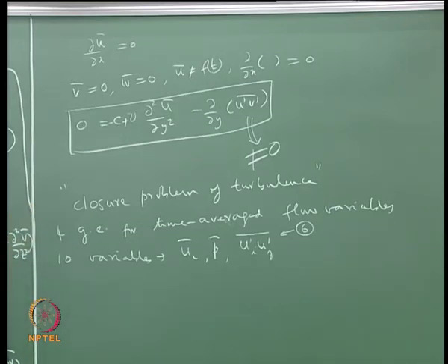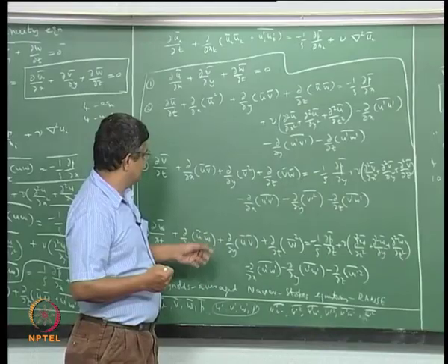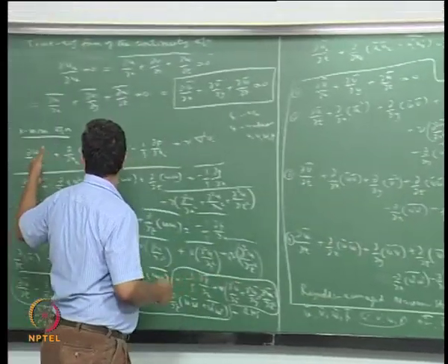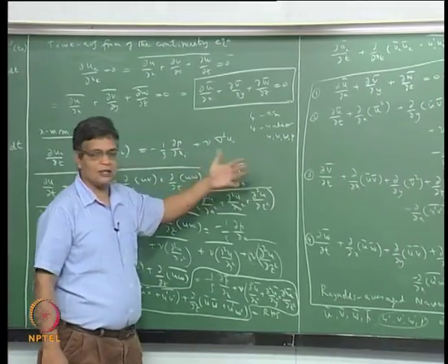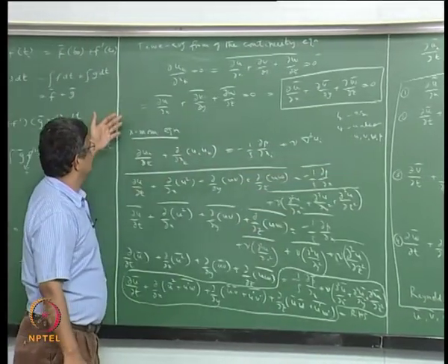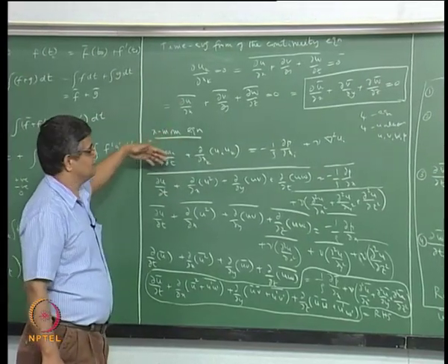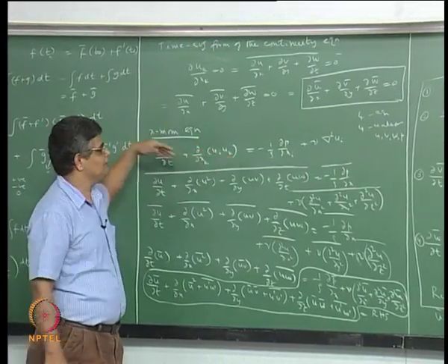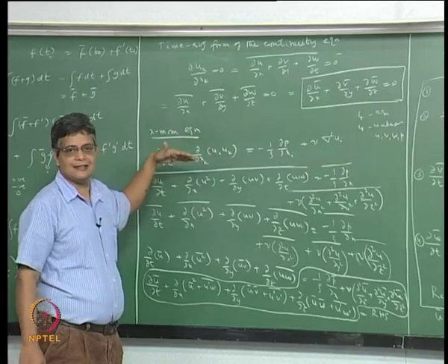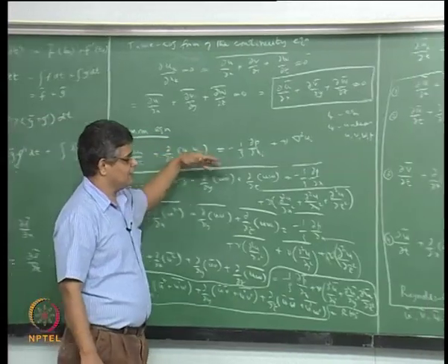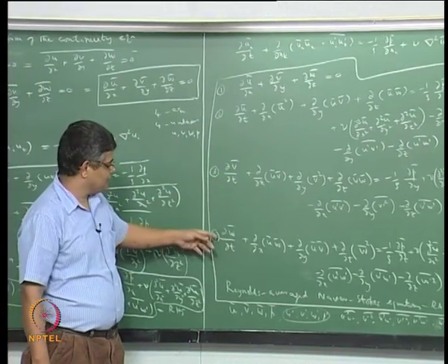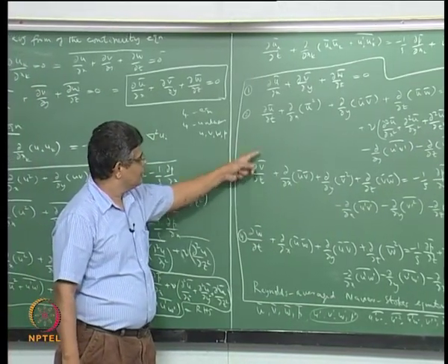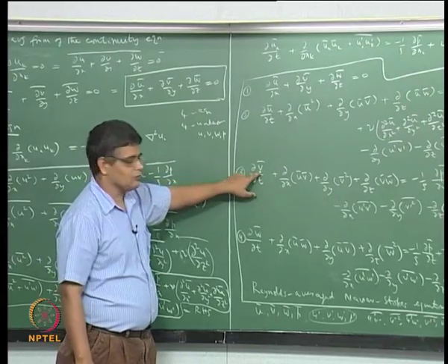One argument that we can make is that the difference between the laminar flow part and the turbulent flow part is fundamentally nothing, because we have just done some mathematical operations here. We have just integrated with respect to time both the left hand side and right hand side, and in the process we have got some extra quantities and expressions for the time average quantities of the velocities.